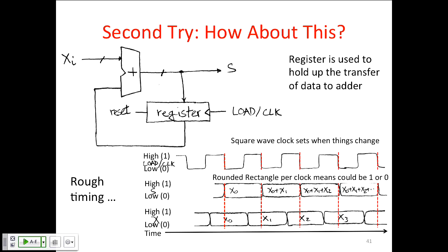At each cycle, you're taking the previous output and adding to it using the adder to produce a value that's going to become the next output, x0 plus x1. So this value plus this value flow through the adder to set up the input to this register for the next clock. Then when the next clock happens, you replace the output with the sum of these two. Then you're ready to add on the next one. So this register is accumulating the total sum between clock ticks.